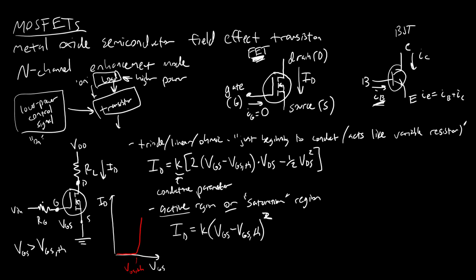But in either case, you can hook one up to a microcontroller to control a load like this. Now in practice, FETs are a newer technology, so if you go read the Art of Electronics, they have a little paragraph about the dominance of or differences between FETs and BJTs, and they say something like 90% of transistors in the world today are FETs, but there are still applications where BJTs are superior, so they have not gone away completely.